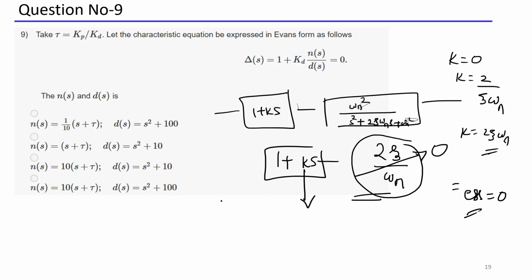Second order system, we are giving you unit ramp input. This is the ramp signal. Solve which is steady state error, which is something like the time constant. So to make this error equal to 0, you have to find out the time constant of the system. Time constant of the system is 1 divided by zeta omega n.